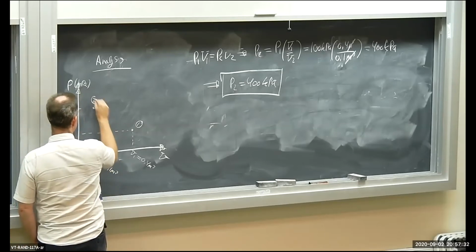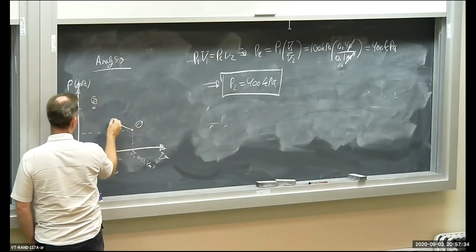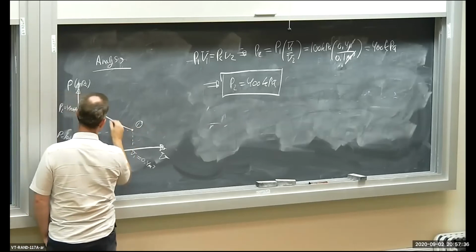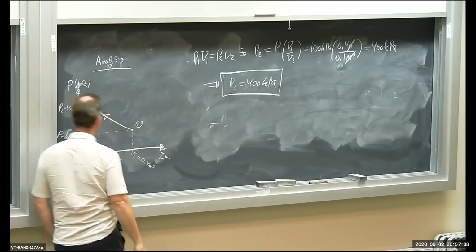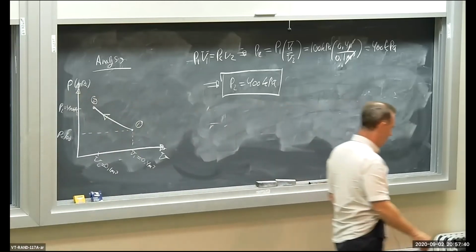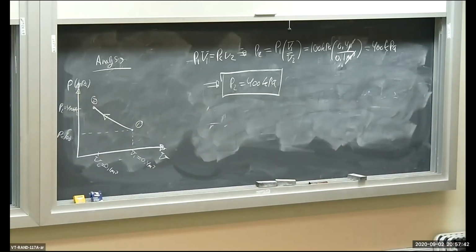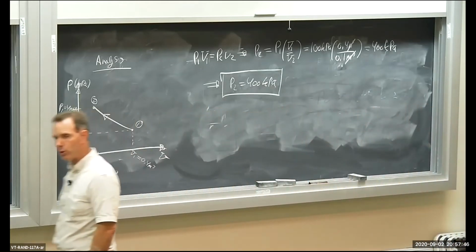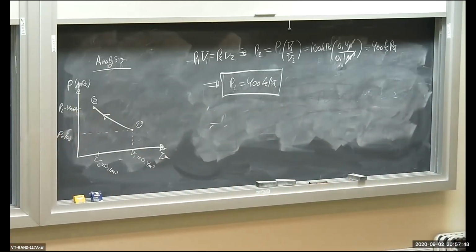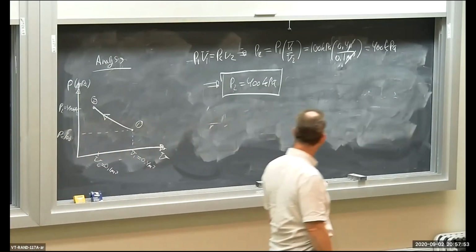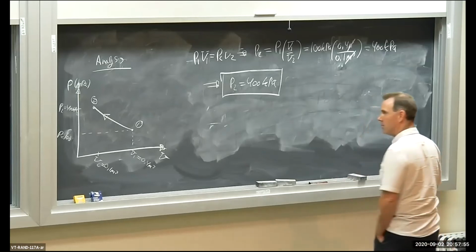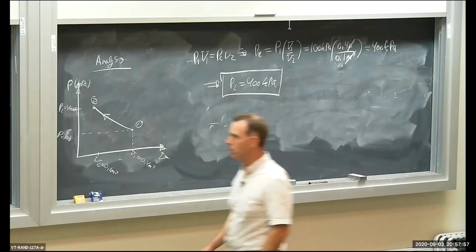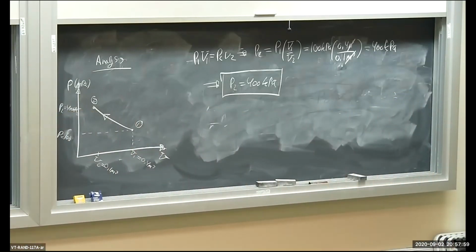So this is state 2. The isothermal compression process looks like that on the PV diagram, up and to the left. It's not a straight line, it'll have a curve to it. So don't make it quite straight. Have a little arc to it, a bit of convexity to it. Okay, so that's P2.